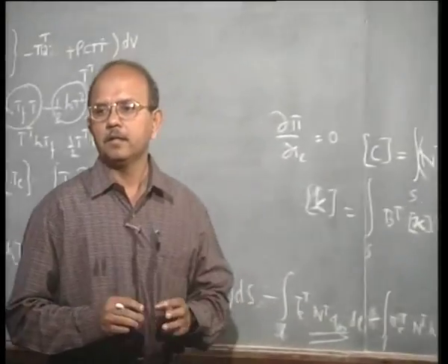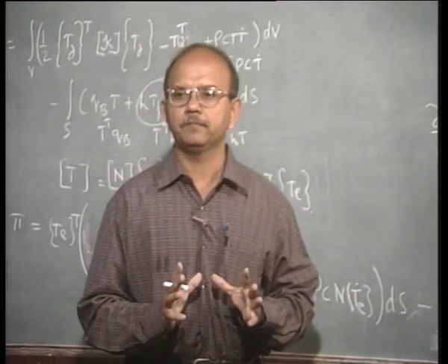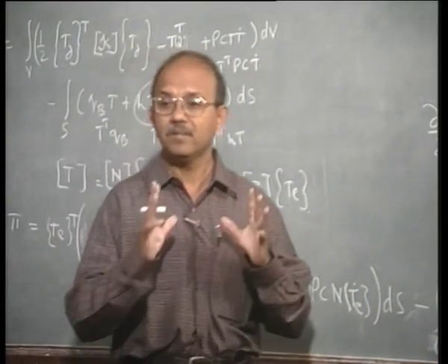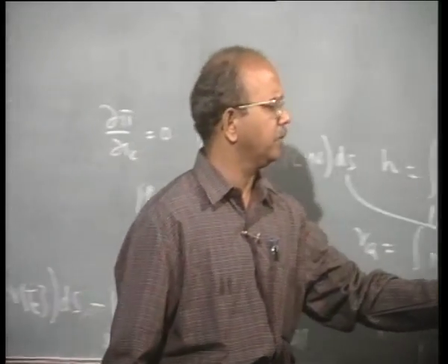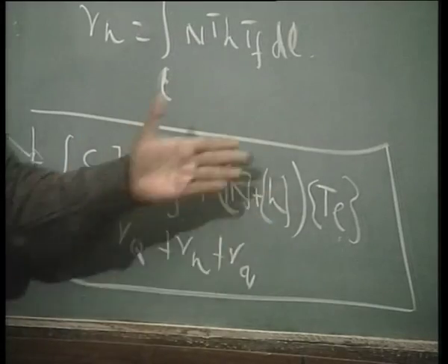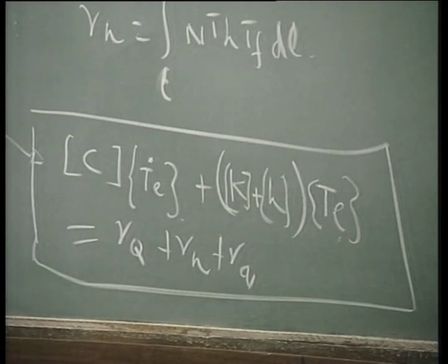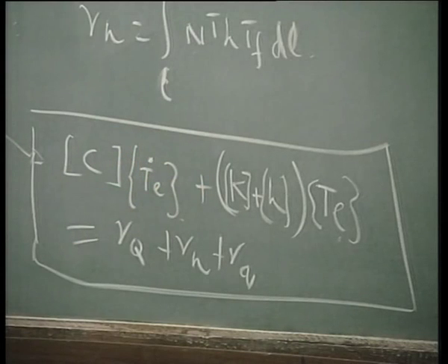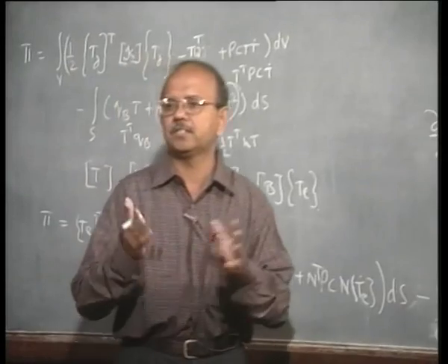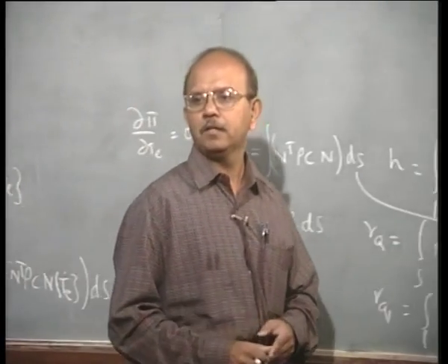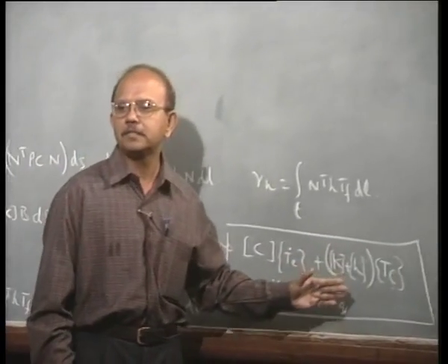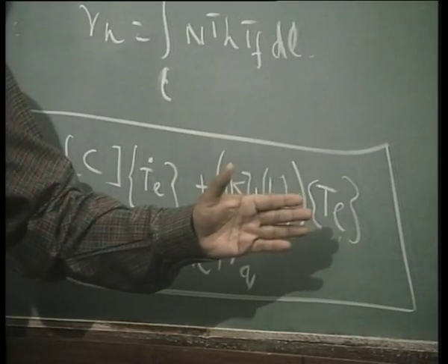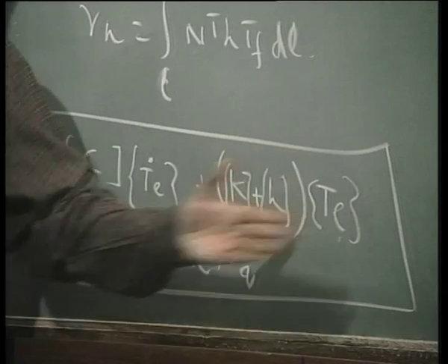Now how am I going to solve this problem? How am I going to solve a transient problem? Steady state problem is simple. If I remove this, then this becomes something like a K matrix. So K T E is equal to some R, simultaneous equations with temperature being specified at some boundary condition. The procedure is exactly the same. Temperature specification is something like a displacement being specified. The procedure of solving the problem is exactly the same as what you would have done for displacement.